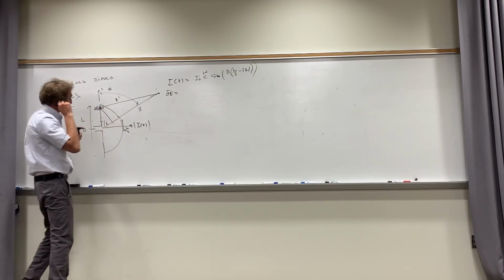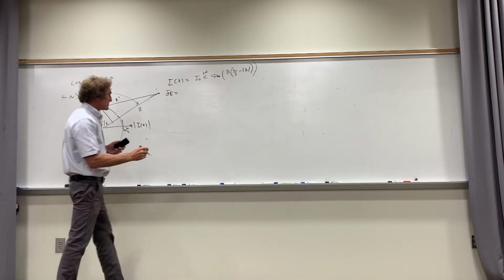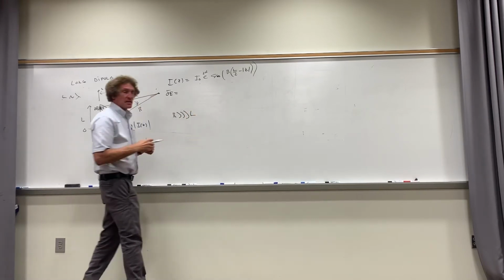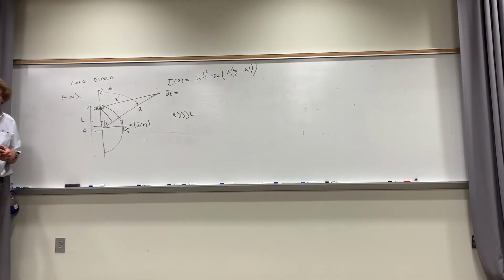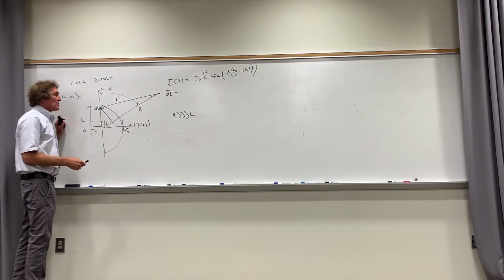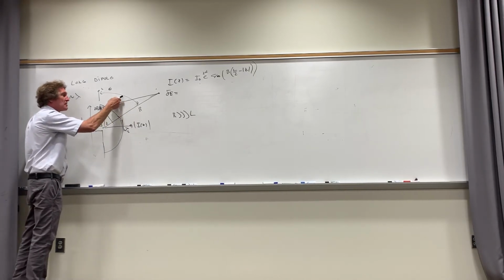I want you to take a look at this just for a second. We assume that r is much, much, much greater than the length of the antenna. In other words, we're a long ways off. It's like if I've got a toothpick up there at the exit sign, and I'm looking at a radius distance from that toothpick at the exit sign back there to me. That's the kind of proportions we're talking about, or greater. Follow me? So if that's the case, you can say that these two, r prime and r, are basically parallel.